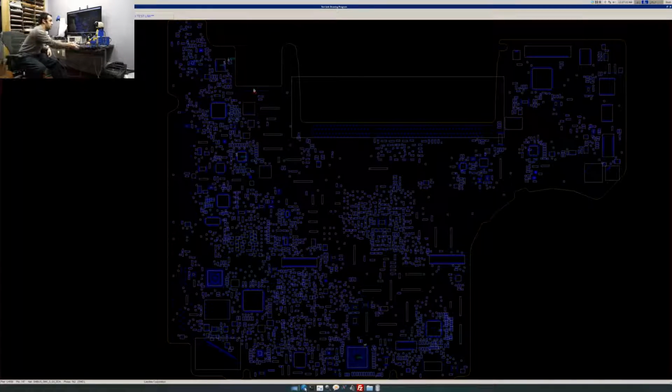So I replaced U7000, and then instead of seeing a question mark or an X on my battery, the battery actually worked. And one thing you'll be able to see with this computer, even after I unplug the charger, it's able to stay on, and it's going to work.